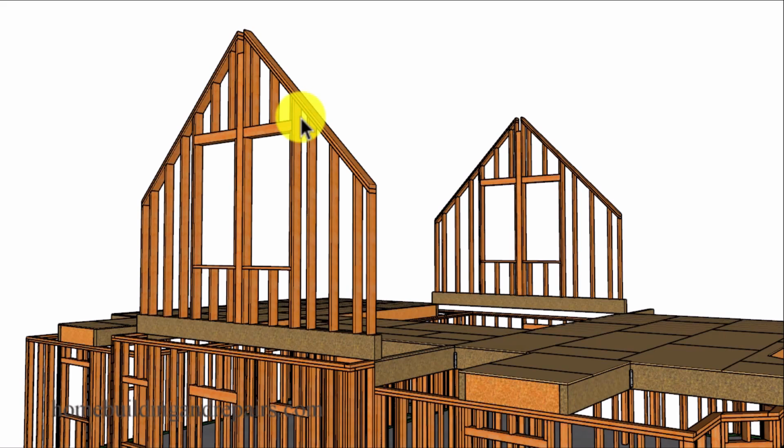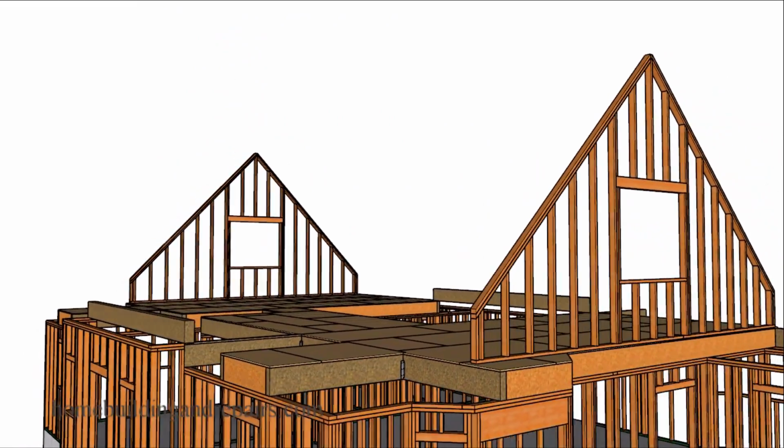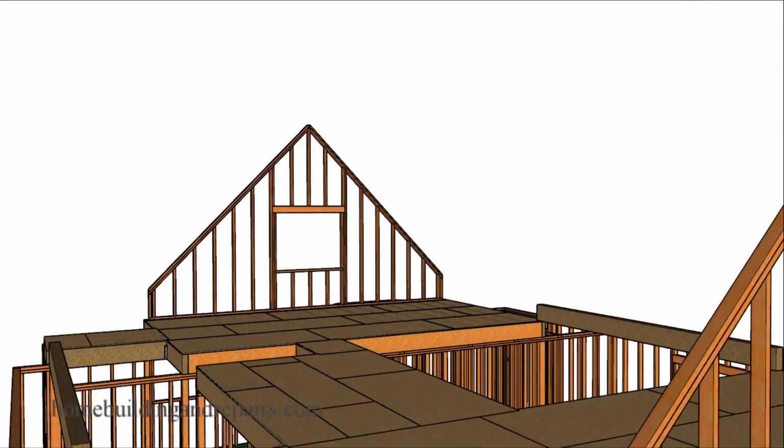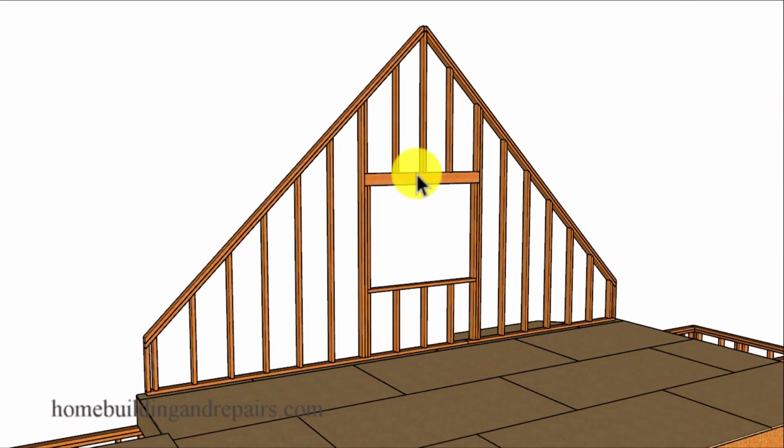And two of those walls will be this one and this one, where they will both be built on top of a beam with 2x6 wall framing studs and a ridge post, a post that will carry the load from the roof framing above down to this beam here, and then of course down through some posts to the building foundation. And of course these two walls here will be built exactly the same also, with a window in the center and a 2x4 to help us support the ridge.